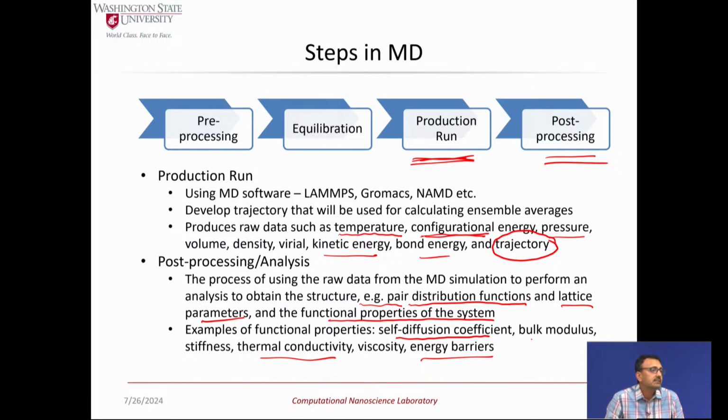But indirectly, if you, for example, apply a temperature gradient and look at the temperature distribution in response to that as the system equilibrates, and if the force field is accurate, the calculated thermal conductivities do agree pretty well with measured thermal conductivity. But no, it doesn't separate out the electronic and phononic contributions, which DFT simulations would be able to do.